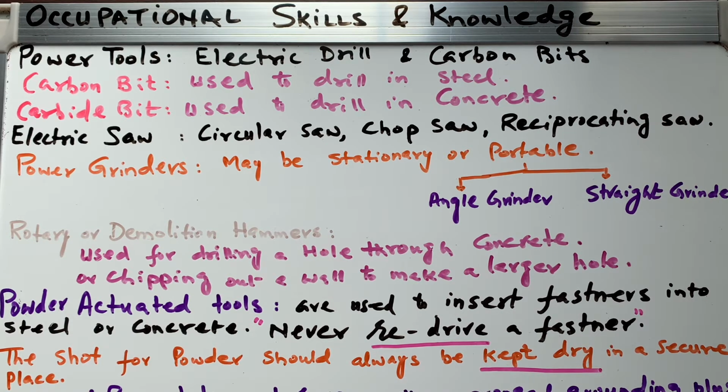And then second is heavy duty electrical drills, which can go from 1/2 inch to 3/4 of an inch. So standard utility drill is 1/4 to 3/8, and heavy duty is 1/2 to 3/4. And then rotary hammer drill, which is used to drill into concrete. In these there is a hammering action in the drill. We call that rotary hammer drill, right?